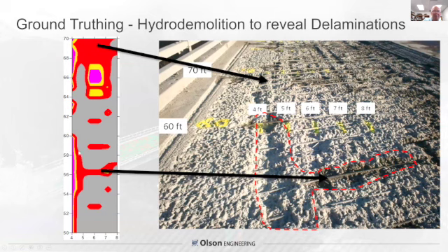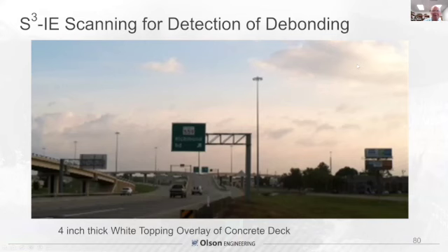And sure enough, what we predicted showed up and was outlined in these photographs here at 60 feet. So we did this initially blind also, and then they shared this photograph with us afterward. So we were predicting this shape of problems, and you can see where the steel is exposed, indicating it was delaminated concrete, corroded, and up here as well in the upper part of this photograph. So it worked, and we've gone on to test other decks with this.